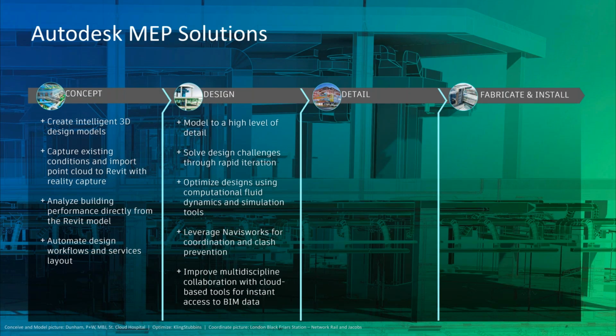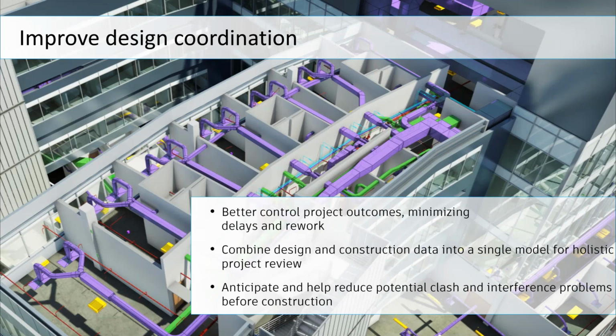When it comes to detailing, the coordination points come in, where you want to run the coordination. Simultaneously, while you're working on the design, you want to run your coordination also. That's where you can identify the clashes in the early design phase, so that you can avoid a lot of rework at the site. When it goes to a complete clash model, a lot of coordination issues will happen at the site. So in the system itself, you can create all the builder's openings or resolve any clashes between the cable tray, the column, or whatever MEP services clash, and resolve everything over here.